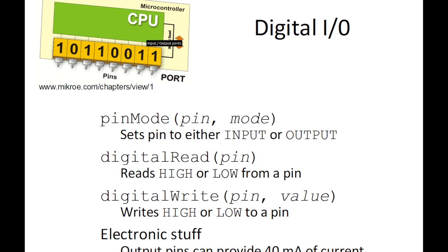And very important information: the output pins can only provide up to 40 milliamps of current. So if you put a load, that's why I was saying, connecting the LED directly can potentially even damage the microcontroller pin, or the microcontroller or the board itself. That's a good idea. Make sure that you limit the amount of current drawn from the microcontroller, but typically it's only a few milliamps. Okay, here it's 40 milliamps.